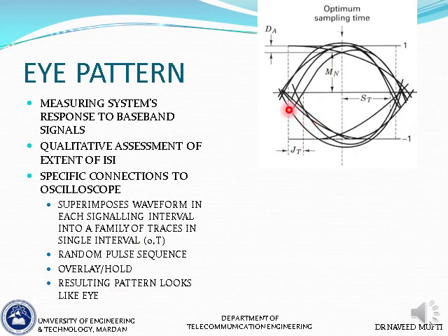Here, for example, we have chosen a two level signal with a positive voltage and a negative voltage. That is some sort of an RZ scheme, maybe an RZL, where a positive voltage represents 1 and a negative voltage represents a 0. Because the pulses are randomly generated, sometimes a 1 is generated, sometimes a 0, so sometimes we have a positive pulse, sometimes a negative pulse. So we have binary antipodal signaling in this example.